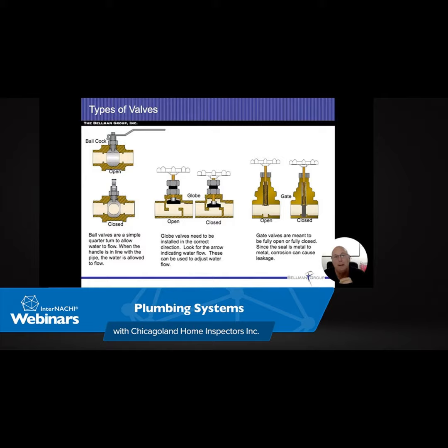The blue that you're seeing in these drawings is water. The brown little pellet things is poop. And if you have it too shallow, the poop and the water is going to stay in the pipe. If it's too steep, the water will get through real fast, but it won't be able to wash the paper and the poop and everything else with it. That 1/4 inch per foot, that's our happy space right there. And we'll have all the waste material flowing, and all the water will go ahead and get that out of the house where it comes to it. So 1/4 inch per foot.